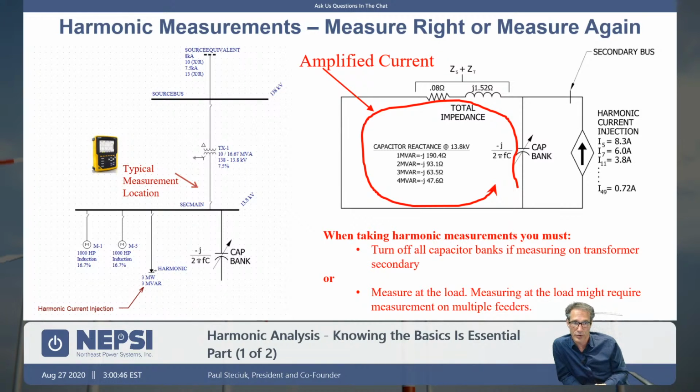Okay, so you have to do harmonic analysis for minimum fault current and maximum fault current. If you have no other data, then your analysis is based on that data, of course. But you can ask questions about the transmission grid. How many miles to the next substation? Try to capture some of the capacitance associated with the transmission line. But you're trying to do the best you can.